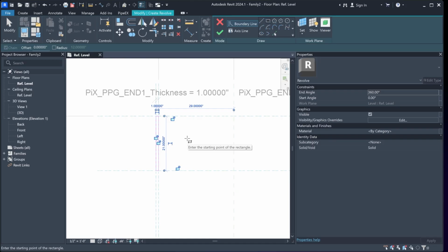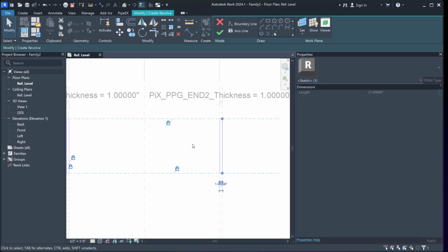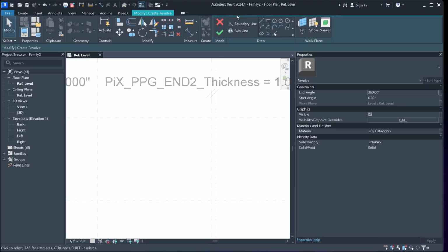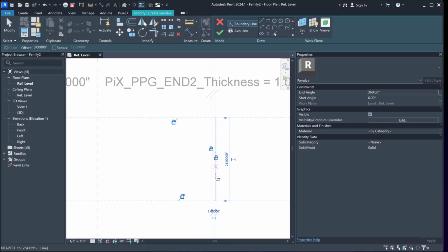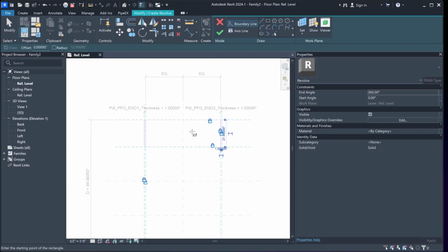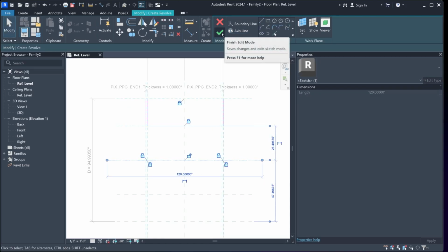Oh, right, yes, I forgot to close the padlocks on the left side, so I'll go to this side again, and it would be easier to delete everything, and then I'll close the padlocks like this. Okay, and then of course we'll need to pick the axis line. So I'll do it like this, and I'll click OK.